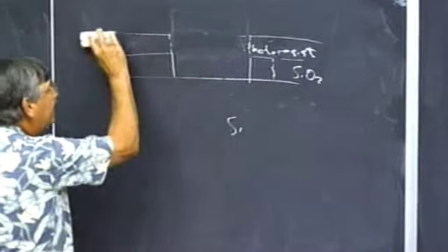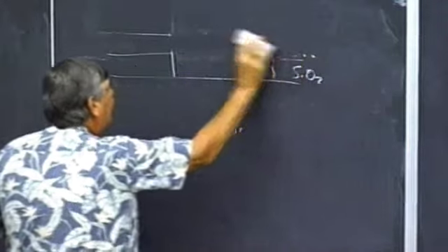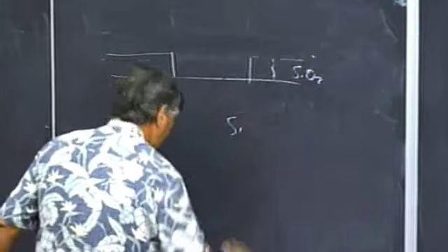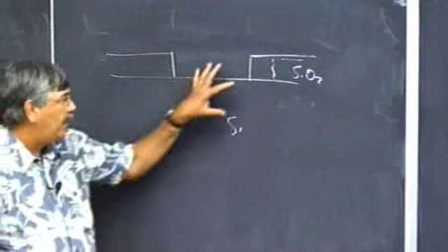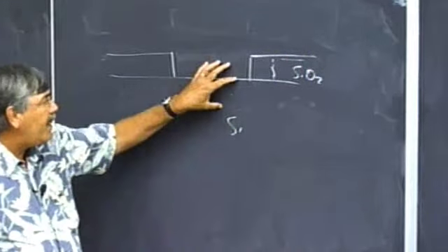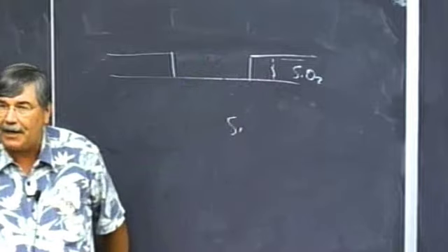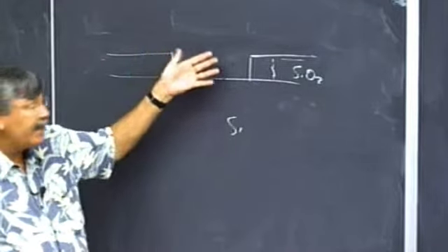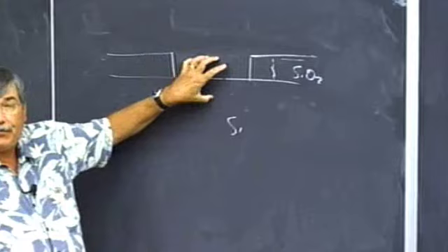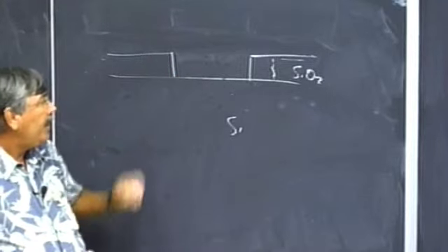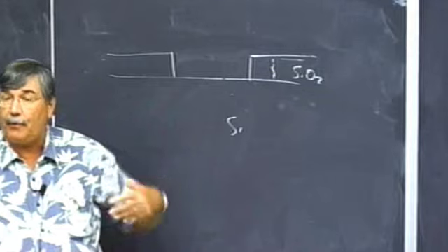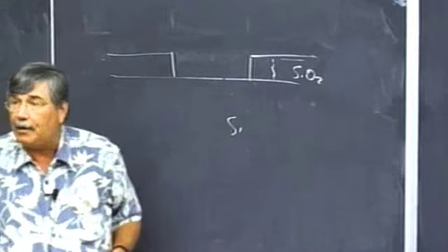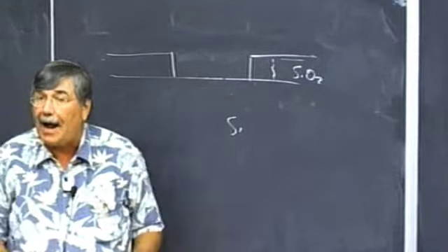And then in most cases we would remove the photoresist. There's plenty of variations on this. But now we've put the structure using a photolithographic process. We've created an opening in this silicon dioxide. And now by one of several mechanisms, we will introduce impurities into the silicon. The most common way these days is to strip electrons off of the atoms and accelerate them in a particle accelerator. That's an ion implanter.